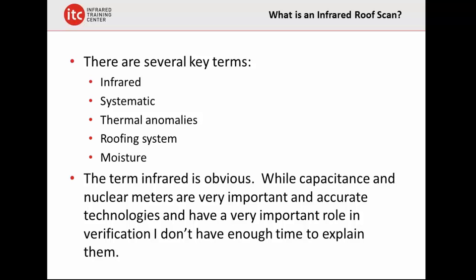And you could do those during the day at any point in time that you wish, but it is only going to give you moisture content. Usually that roof is gridded out. So you say, I'm going to take a point measurement every 3 feet, every 4 feet, every 5 feet across the entire roof. Well, if you have a small patch of insulation, and we'll see one here in a little bit, that was only about 1.5 feet in diameter, you just might go right over that and miss that. So they're not always extensive. They tend to identify very large issues, but they can miss the very, very small ones.